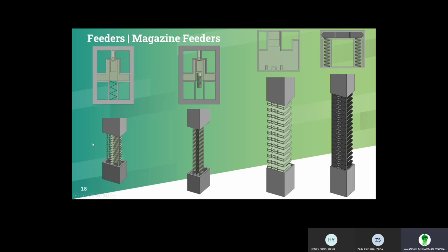The mechanism is that it comes in pairs, so one magazine feeder set will have a tray and a catchment tray in front of it. One will slide down and be transported to the catchment tray, which is the contact point for the robot to pick it up.